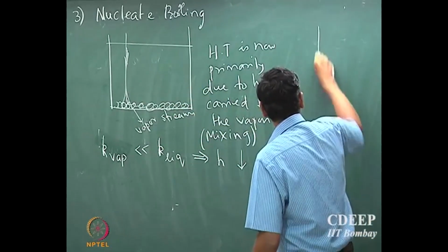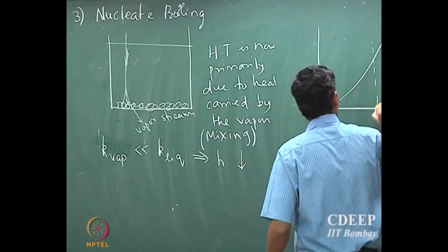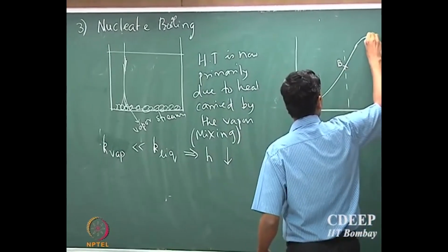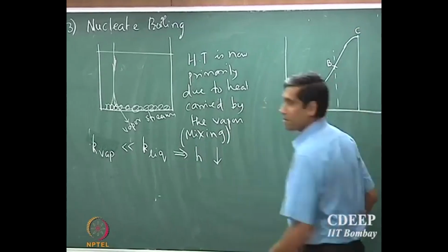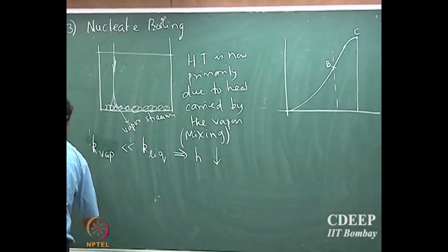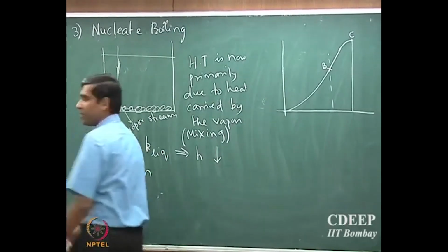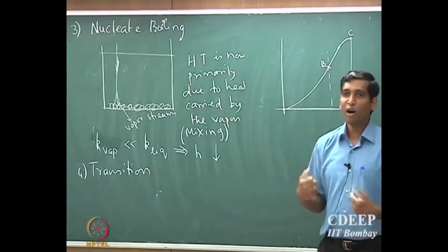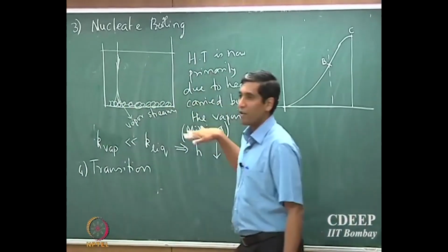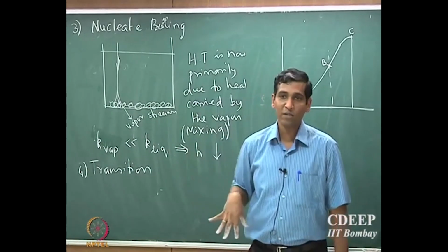Okay. And the boiling curve here is, so if I put, so that stage is all the way up to the maximum. Okay. And what happens after that is called the transition stage, okay, where you cannot distinguish whether the bottom surface is now in contact only with the fluid or only with the vapor phase.